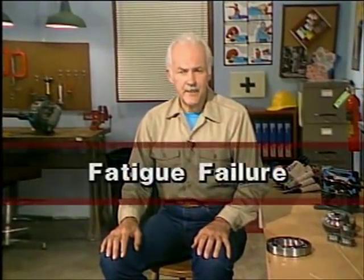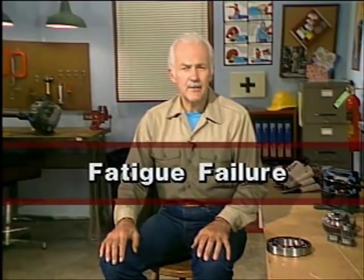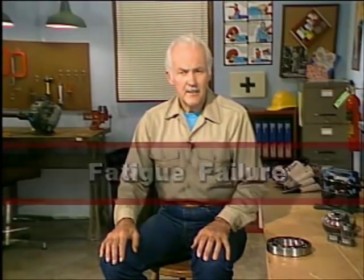All of the conditions that we just mentioned can lead to early bearing failure. And if a bearing fails, it can result in a lot of damage to the gears in the unit. One type of gear problem is gear tooth breakage. There are several ways in which a gear tooth or teeth can be broken. One way is through fatigue failure. Fatigue failure usually results from repeated bending or flexing of the gear teeth. Let's look at an illustration to see what can happen.